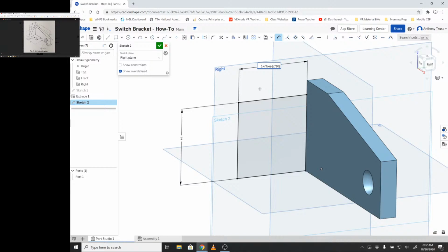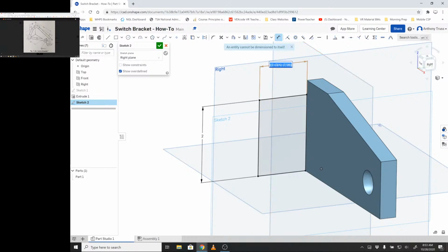So at this point, we have an expression line that should work. I would like to wrap all of this together, so add one more parentheses on one side and add it to the other. So now it's just one encapsulated expression. If I press enter, I have my value at this point, and that's exactly what we should get. If I were to double click it, you would actually see the fractional information that you put.